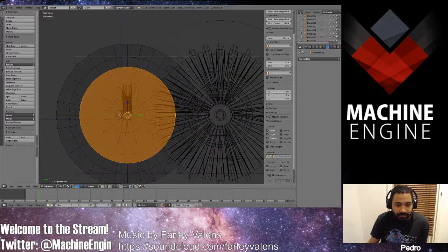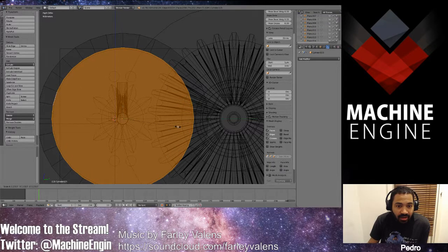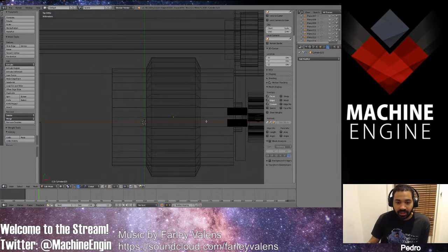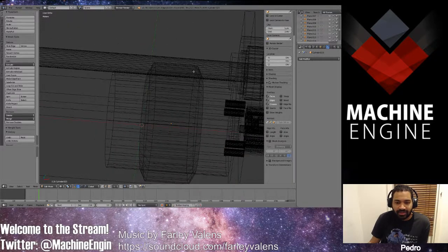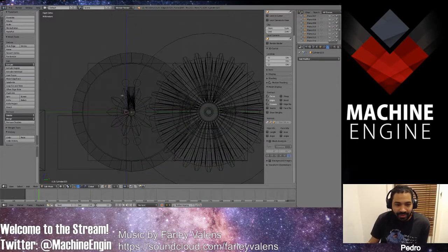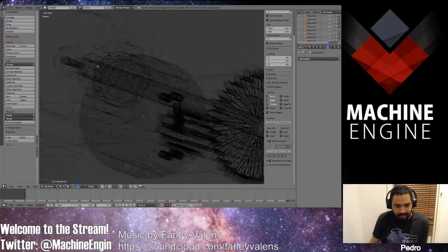Now what I want to do is size it back up just a bit over the motor. You gotta watch out with 3D printing because there's a discrepancy in the model sizes. Ooh, I actually kind of like that slope. I'll leave it. You gotta watch out with 3D printing because it's like a 1 millimeter discrepancy. If you make something too precise, because of thermal expansion and cooling off and all kinds of stuff, your model is probably gonna be off. So watch out for 1 millimeter tolerances.